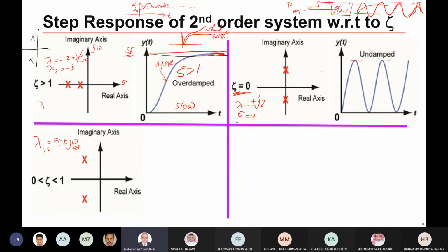So we have oscillation, and we have also damping, and this sigma is negative here. So the response would be as such. You have here maximum overshoot, and then this peak is lower than this peak, definitely. Then we have some damping, and we approach the steady state. And this system is stable, and these eigenvalues are in the left-hand side. We will discuss the opposite case now.